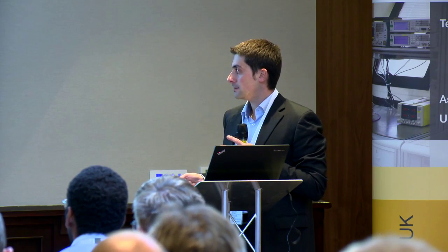On the output side, we basically have the ability to measure all the tones composing this signal and to control arbitrarily in amplitude and phase all the tones that are composing this signal. So by adjusting the amplitude and phase of each one of those tones, we can arbitrarily control the gamma at the device reference plane.